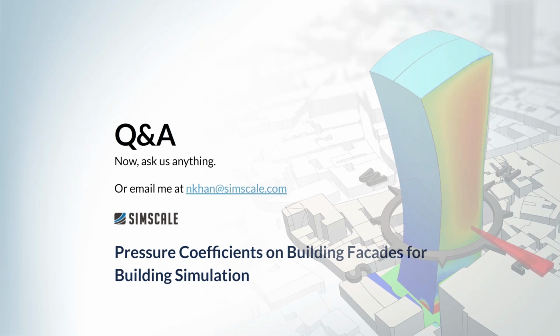Right, and wind tunnel testing, as you know, is highly simplified. It's mostly designed to capture the behavior of the flow around your building, and that data was then used by other software vendors, who have interpolated and extrapolated it to apply to any building. So there are inherent errors there. It also doesn't account for turbulence and the context properly, as we said, and the corrections that they suggest, like exposure types, are poorly understood.